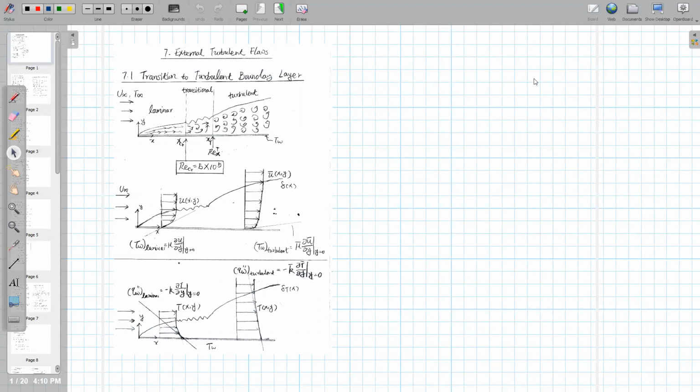if the flow becomes turbulent, all those hydraulic and thermal correlations that we derived before, like the friction factor and the Nusselt number we developed for laminar external flow, like laminar flow over a flat plate, and laminar internal flow, like fully developed laminar flow inside circular pipes, those correlations will become invalid, and we will have new correlations to use. So these are the 2 questions we are going to solve in this lecture.